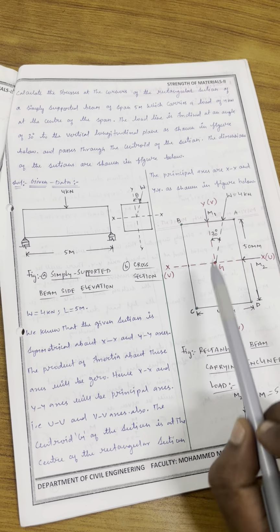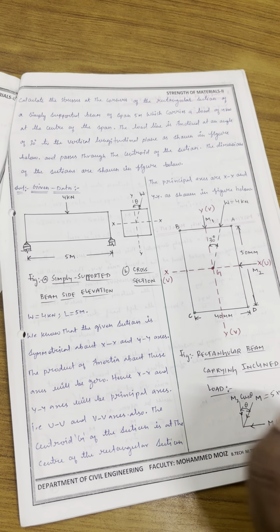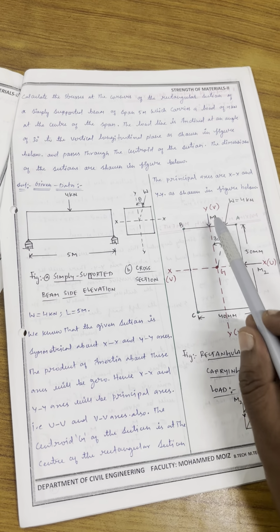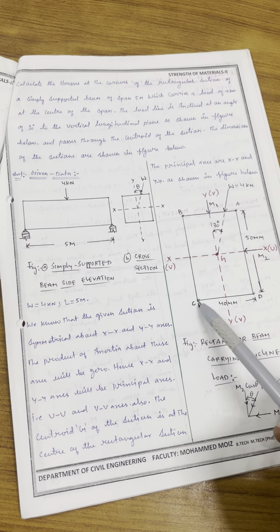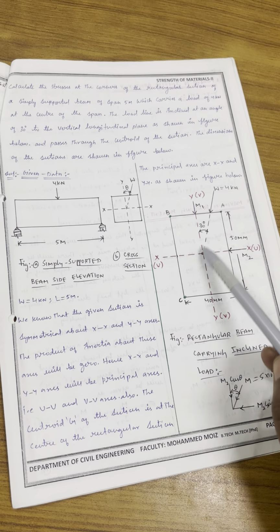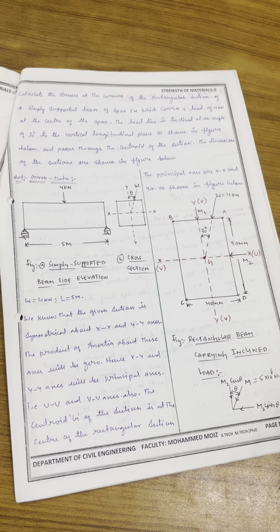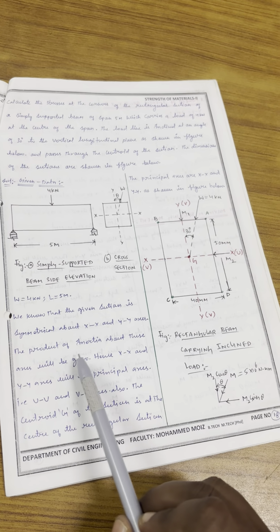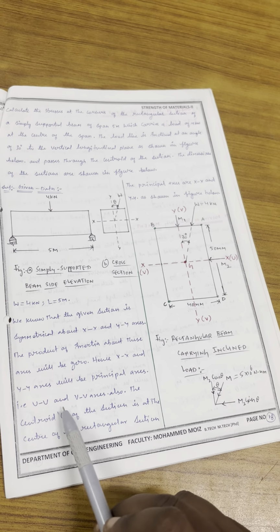If the corners are A, B, C and D, the width is 40 mm and the height is 50 mm. The angle is 30 degrees, the load is 4 kilonewton. Now we need to find the stresses at A, B, C and D. As it is symmetric about xx and yy, we can write uu and vv. Given that the section is symmetrical about the xx and yy axes, the product of inertia Ixy will be equal to 0. Hence the xx and yy axes will be the principal axes, that is UU and VV.